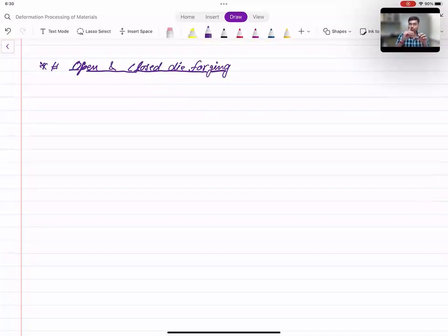That portion is known as flash, and it is a sort of defect. Actually we should not call it a defect, because it may be beneficial also. It acts as a buffer zone where we can keep the excess metal, so that the cavity gets filled properly.